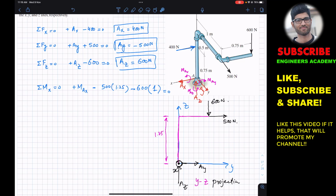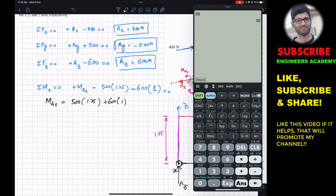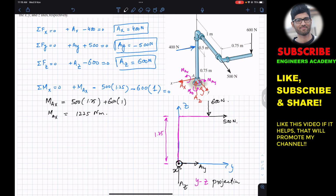I hope this helps you in understanding how to write this particular equation. So now we can write that MAX, the couple reaction at A about the x-axis, is equal to 500 into 1.25 plus 600 into 1. This gives me 1225 Newton meter. This is the couple moment reaction at A about the x-axis.